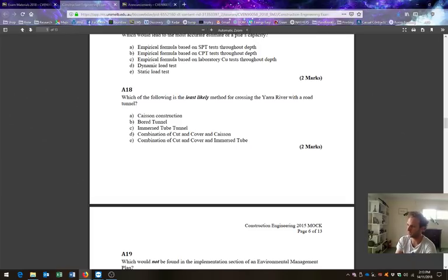So 2016 exam B2E, recommend a bridge construction method and deck support system for a bridge that is to have 3 240-metre spans with towers above the deck. So this is based actually on Jeff Taplin's lecture, and it's essentially an arch bridge or a box girder arch bridge, and that's because we can't go to cable stay because we can't have the towers above the bridge deck. So have a bit of a look through Jeff Taplin's lecture. It's a bridge up in Brisbane, and he talks a little bit about that one, so worthwhile checking.